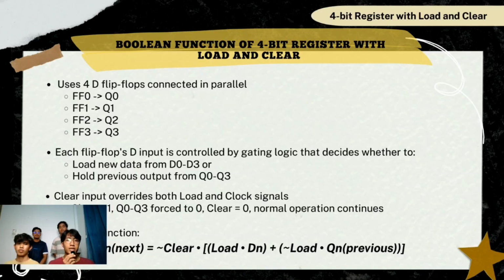And each flip-flop's D input is controlled by gating logic that decides whether to load new data from D0 to D3, or hold previous output from Q0 to Q3.